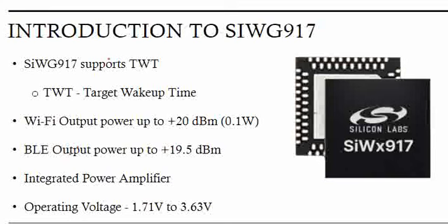We'll talk about the feature in the next videos, but to give a glimpse of what it is, basically it is the time for which a device can be in sleep mode, and then it wakes up based on the data that is available on the wireless interface, and again it can go to sleep mode. The kind of intervals that the device can be in sleep is all covered by target wake up time. We'll talk in detail on this later.